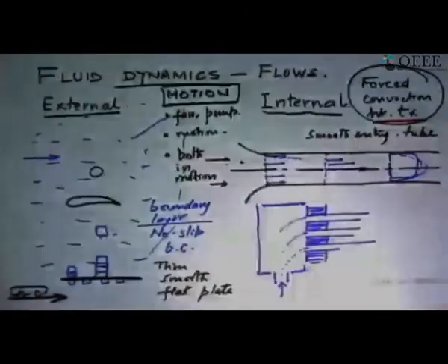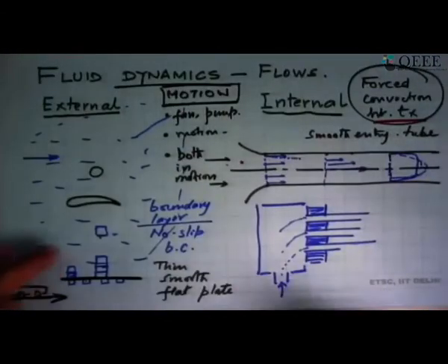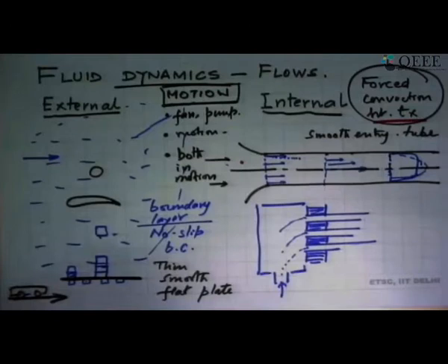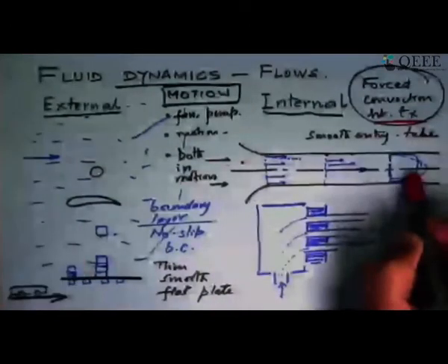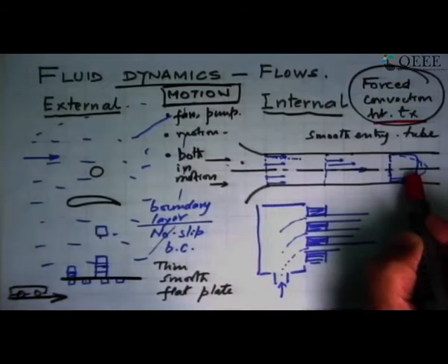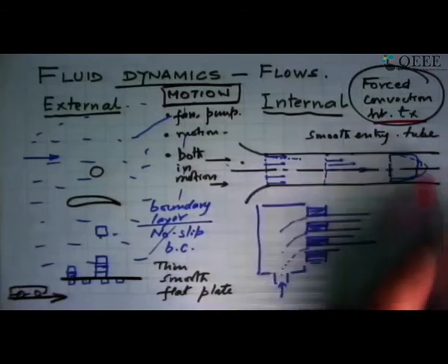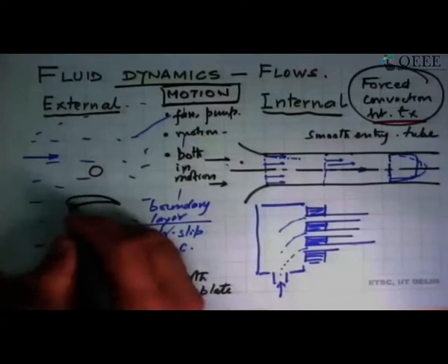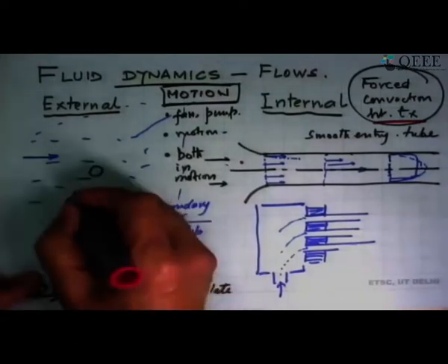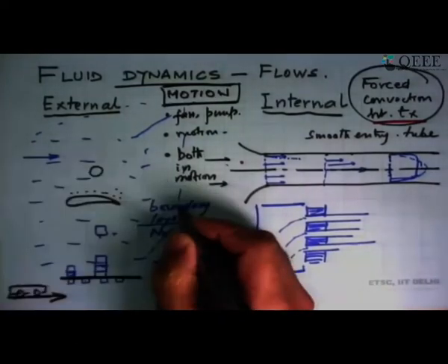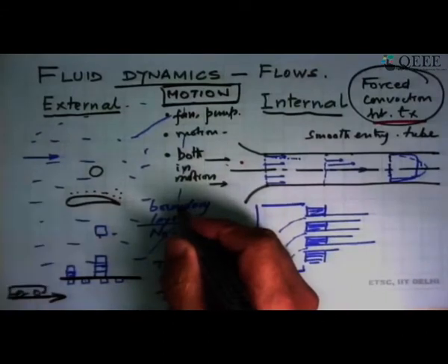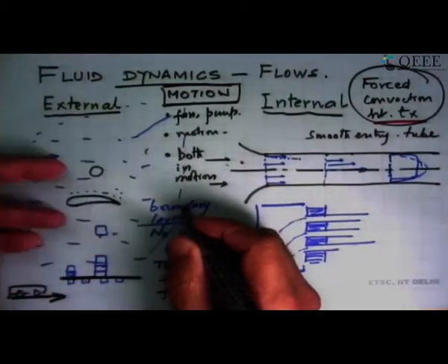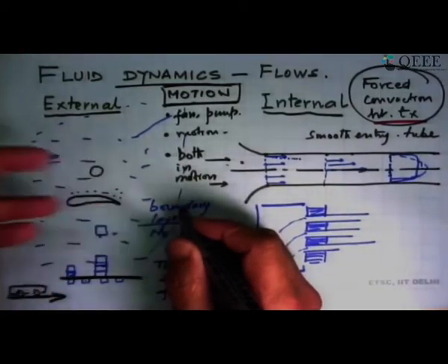What it tells us is that when we mean by, say, forced convection, the temperature fields that the fluid experiences do not generate anything which affects the fluid mechanics. So if in this case, say the airfoil were hot and the air outside was cold, then as the air went out, the air got hot. And what we are saying is that that temperature change of the air does not affect the flow that was happening on it. The boundary layer and the fluid, that is not affected.